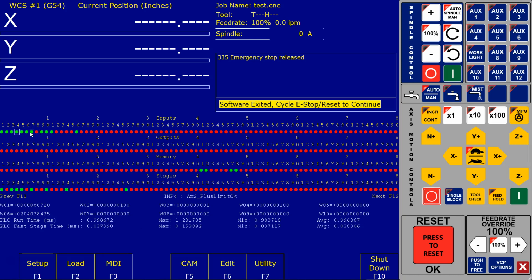So if I closed that input now, you can see that that goes red. And if I go back and invert it again, just by doing Control Alt I, it's now in a closed state and it goes green, because when it was closed, it's now green. Okay, let me open that switch up again. All right, so one can easily invert an input just by moving it over or highlighting that particular input and issuing the Control Alt and I.